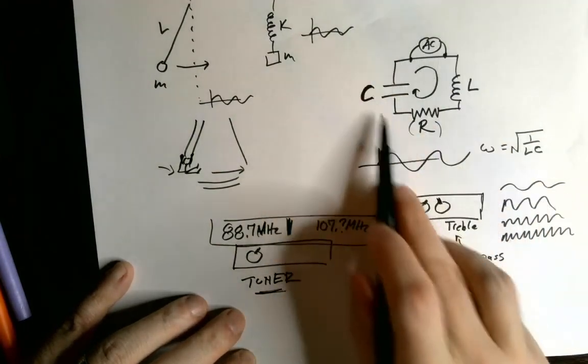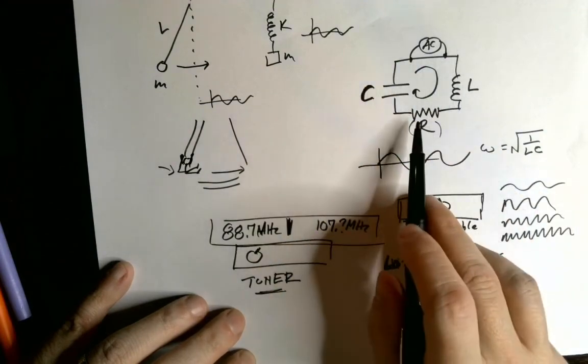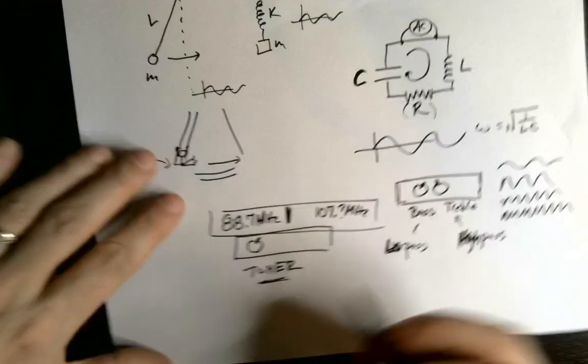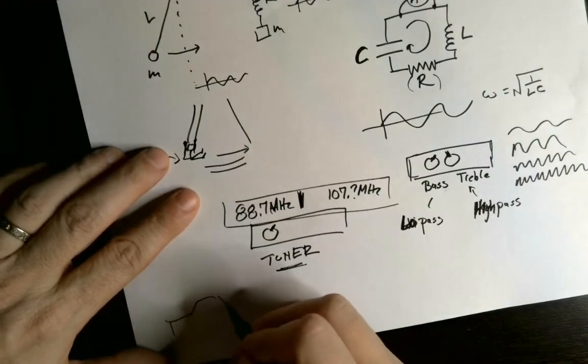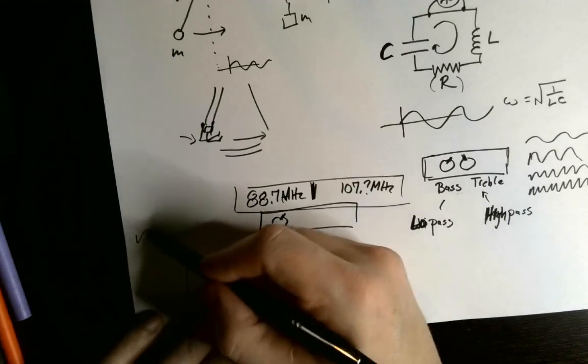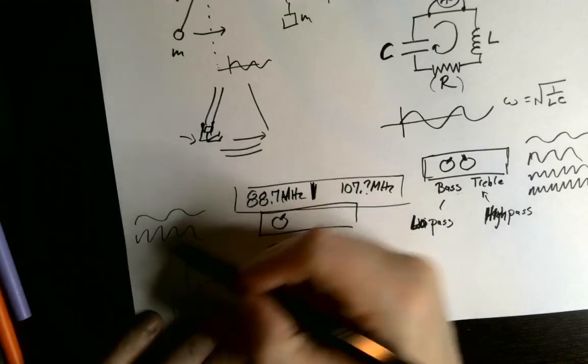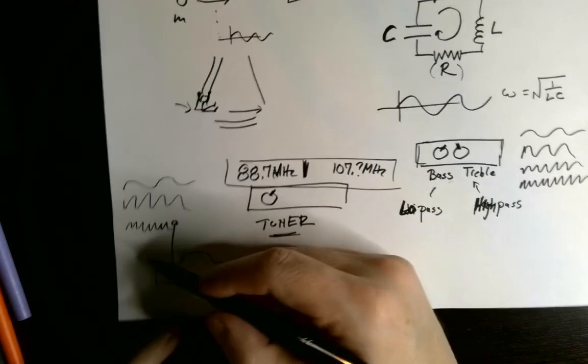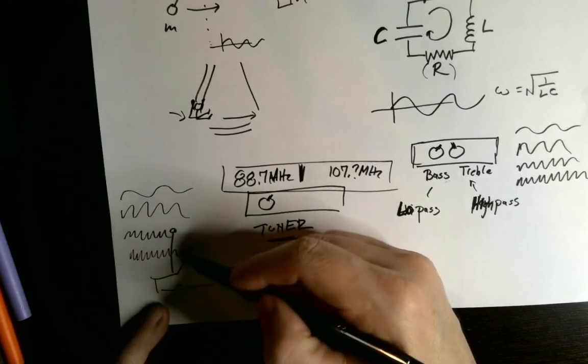to change the resonant frequency of the circuit that picked up the electromagnetic waves from the antenna. Your car has an antenna that sticks up in the air. There are electromagnetic waves of all different frequencies impinging upon that antenna and causing the electrons in that antenna to move back and forth in all sorts of different ways.